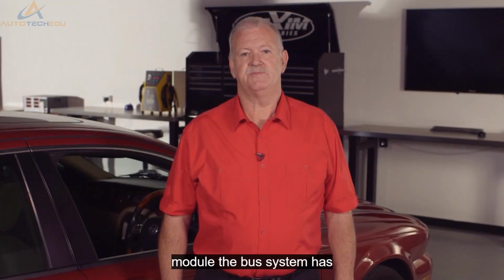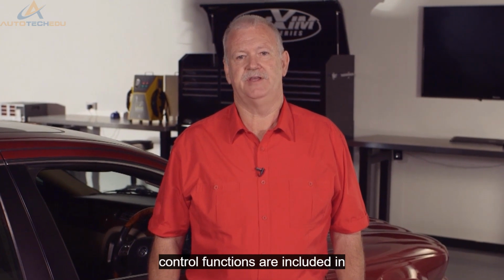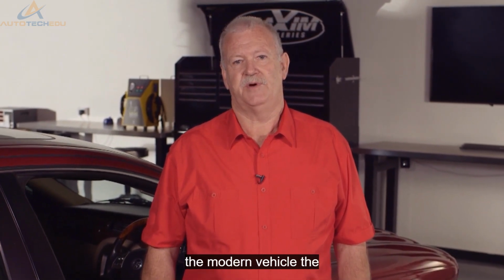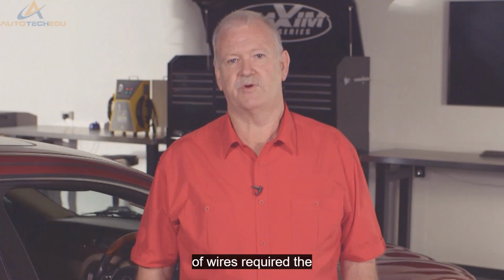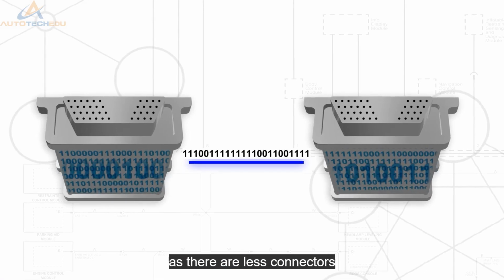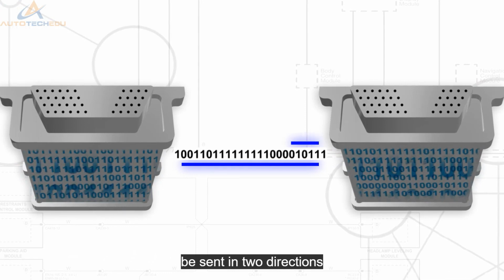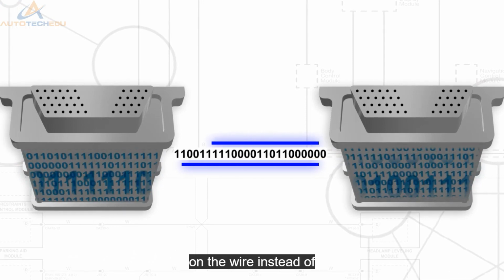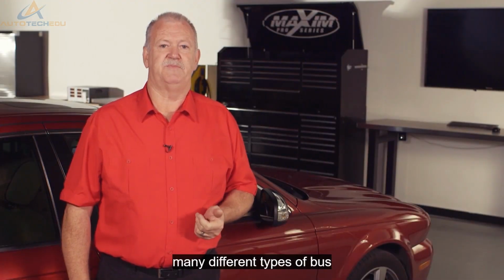The bus system has many advantages. More module controlled functions are included in the modern vehicle. The bus system allows locally placed modules to do the computing. This reduces the number of wires required. The system is also more reliable as there are fewer connectors and wires to develop faults. And the information can be sent in two directions on the wire instead of just one, as in the old networks. There are many different types of bus systems.